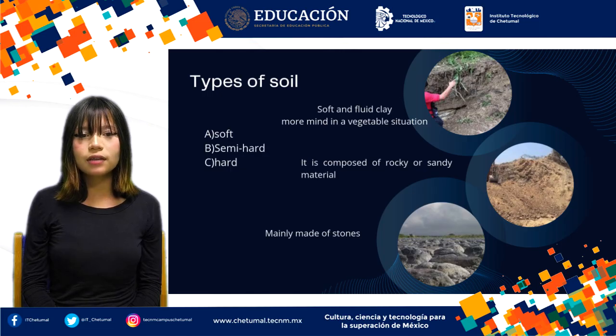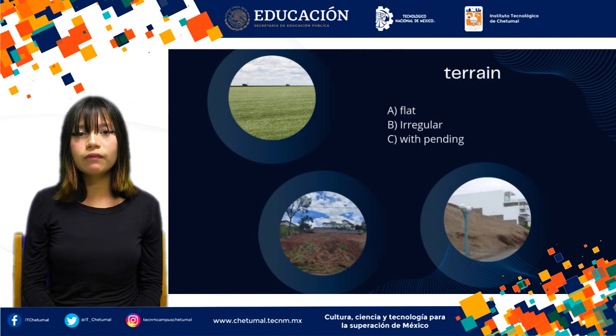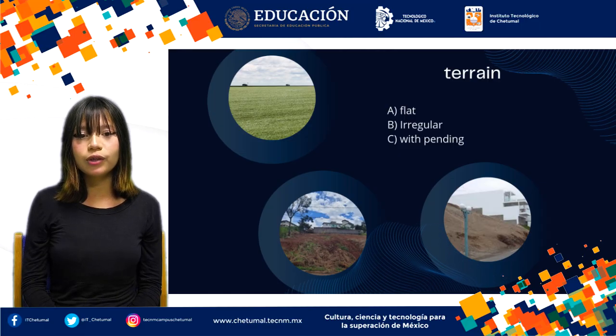Use of theodolites and laser levels to ensure that the marked lines are perfectly horizontal and aligned. These tools allow precise alignment of stakes and strings, avoiding unwanted slopes. Level control. The leveling process ensures that the working surface is at the correct height. This step is essential for the stability of the foundation. Height differences between various points on the land are measured and adjusted to achieve a uniform level.